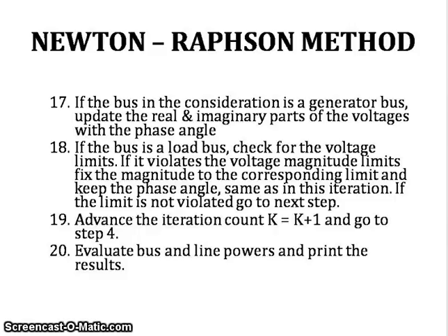What exactly are we doing? We assume the slack bus voltage 1 per unit and the angle delta equal to 0 to fix the slack bus. Then we assume V and delta at all PQ buses and delta at all PV buses. We compute delta P_i for PV and PQ buses, delta Q_i for all PQ buses, and we calculate the active and reactive power P1, Q1 for bus 1, the slack bus.